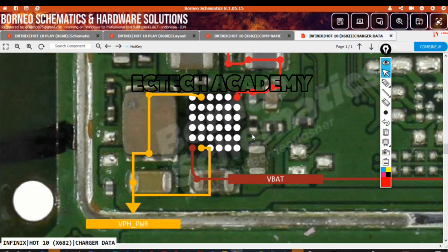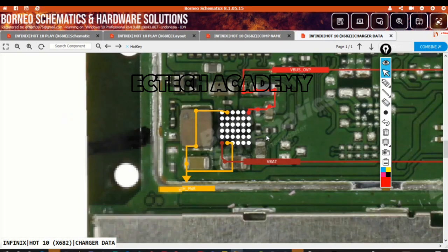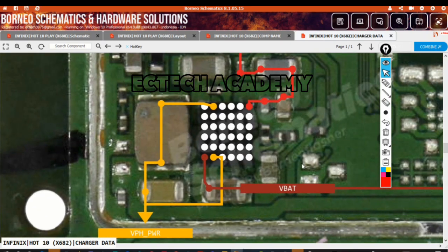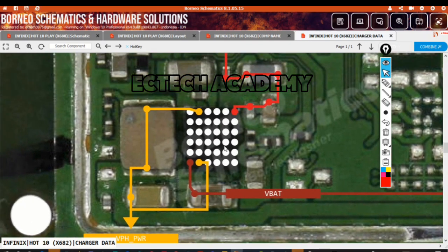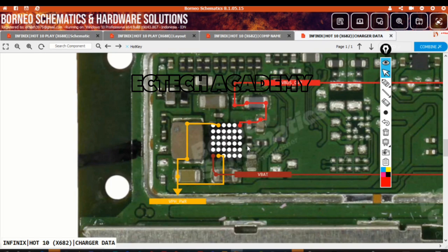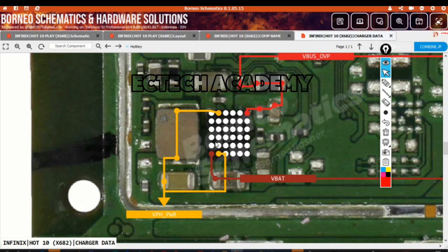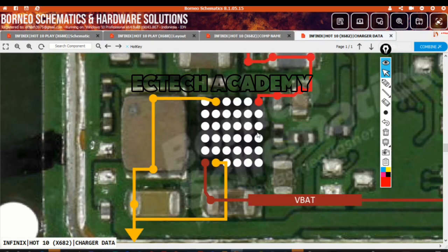But when we go deeper into schematics understanding, there may be a possibility that the charging IC is good, but the feedback voltage will not be out. Why? Because the charging IC is not receiving some signal. So that's pro level of schematics understanding. In that case, we have to go to the architecture, the diagram of the charging circuit.